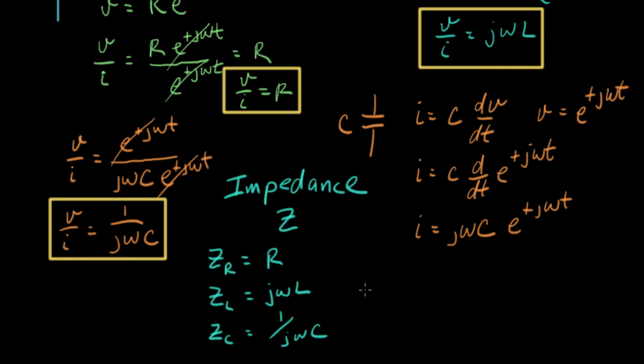And as a reminder of the assumptions we made, we said that we're only going to consider sinusoidal inputs. And what we did is we broke up our sinusoid, our cosine wave, into these. We looked at how these rotating vectors pass through our components in the form of voltages and currents. So there's no new physics here. What happened was we took these j omegas that came out of the exponentials when we took the derivatives. We associated those with the component itself. We did that here and we did that here, and you can see it here.